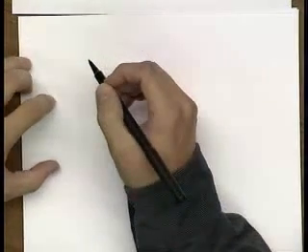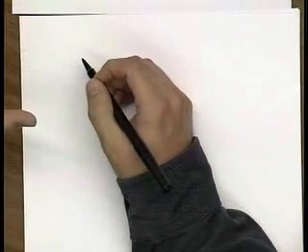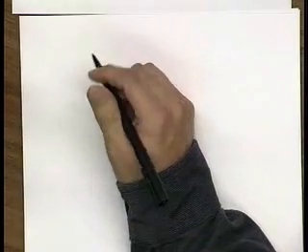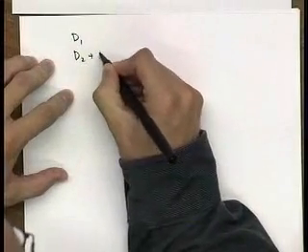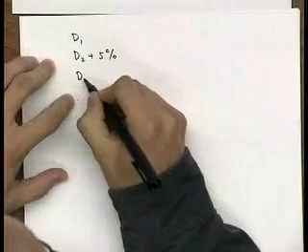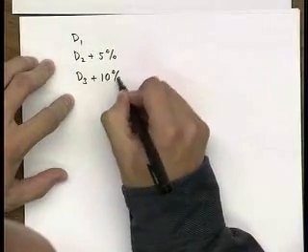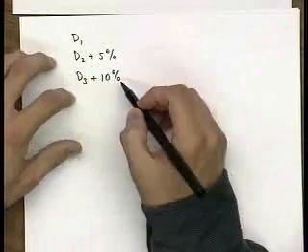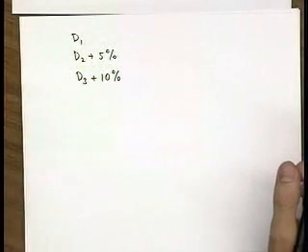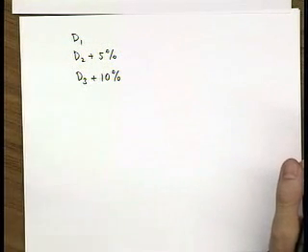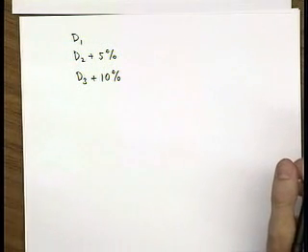So now what we are going to do is say, well, let's assume that we have some slack in our design, and given that timing, I'm going to assign my delays maybe D1, D2 plus 5% of the minimum, and D3 plus maybe 10% of the minimum. So now if I can tolerate some discrepancy in the delays, I can certainly reduce my energy. And the question again for you is, what's the optimum sizing strategy to minimize energy under these delay conditions?